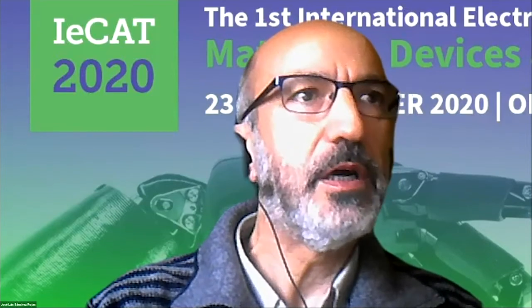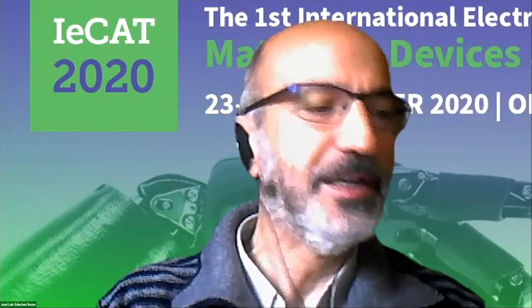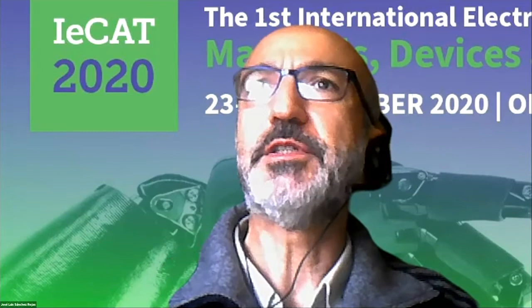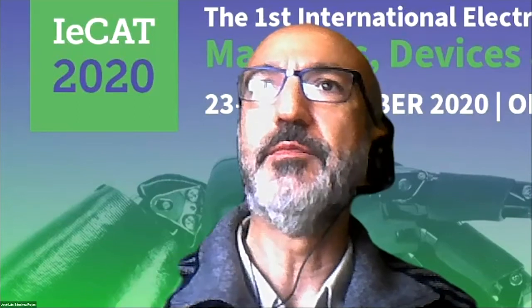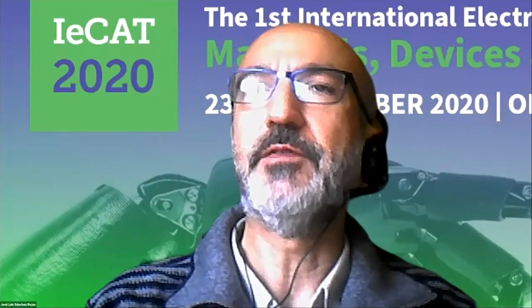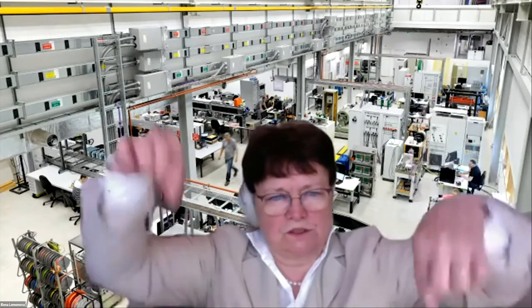I have one more question, about the feedback in the position. How do you arrange the feedback for this positional precision? Is it based on optical sensing? Yeah, it's an evolution of many types of sensors. At the beginning, we were using eddy current sensors and capacitance sensors, and then we moved to laser interferometers, and then we introduced on top of the system a multi optical laser system with tracking points.